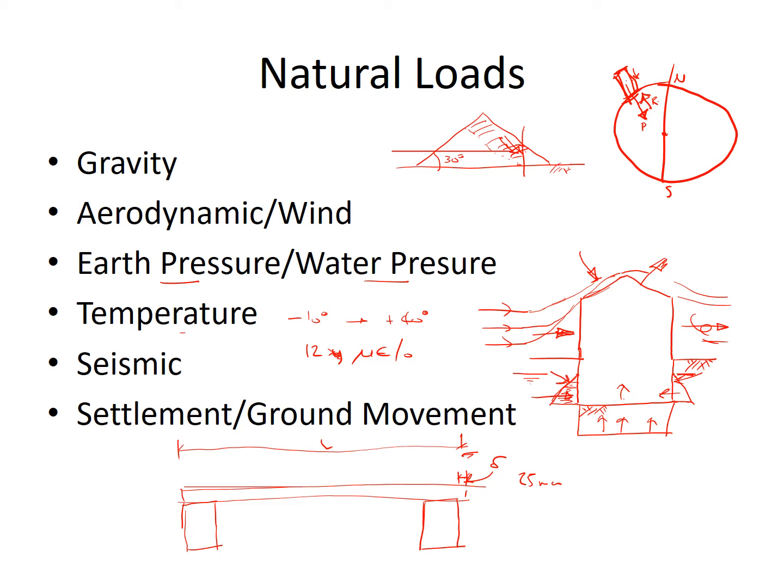And the consequence of that is that these abutments just aren't capable typically of providing that kind of resistance. So the reaction that you're requiring these abutments to provide to resist that expansion is just not capable of being designed very easily.